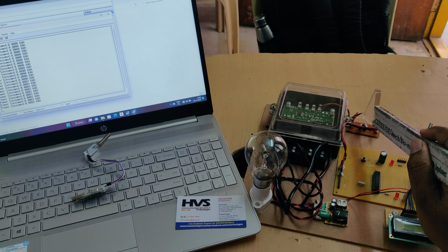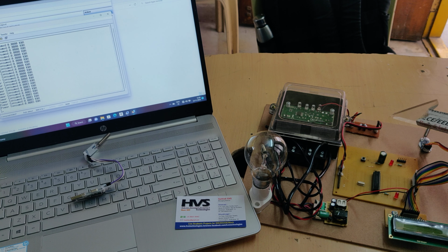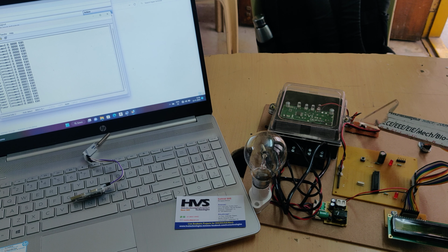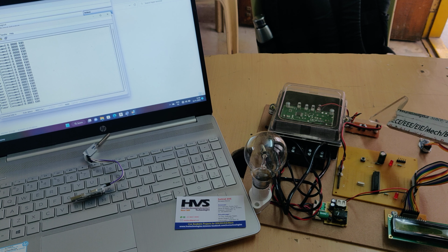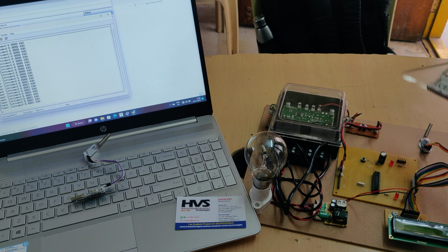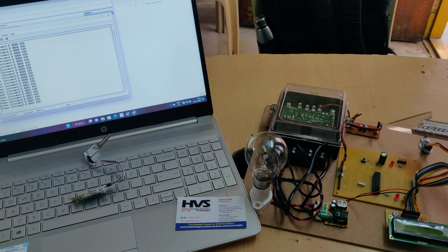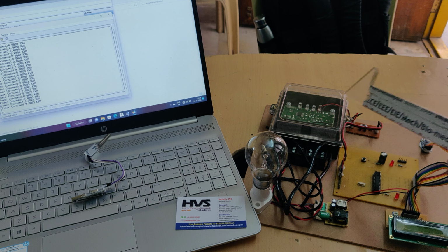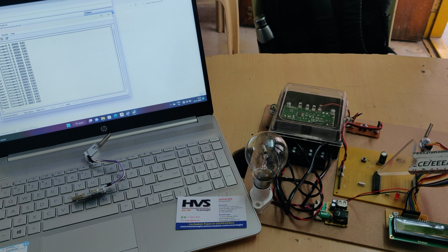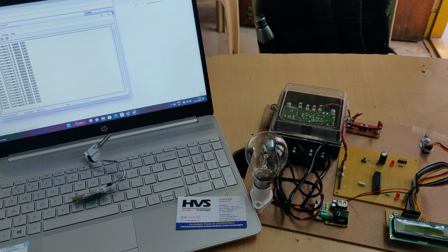In this IC we have the LED on one side and a phototransistor on the other side. When this LED is on, the LED inside also gets switched on, so on the other side the phototransistor gets affected, and that provides the pulse input to the microcontroller. Means the same pulse will be converted into an optical pulse and then back to electrical pulses. So this is the main secure device between the controllers. Only if high current is generated, this IC will get damaged, so that we can protect the microcontroller. Next, we have interfaced the ZigBee module.